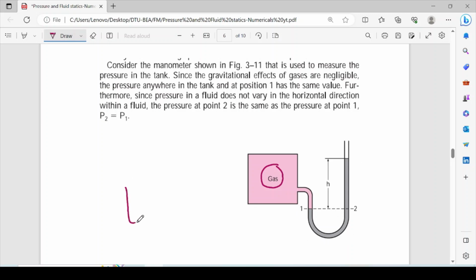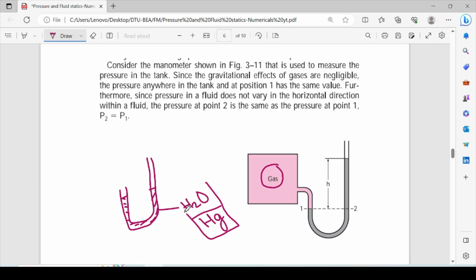Initially, this U-tube manometer is like this, and in this we are filling, initially both ends open, a fluid, either water or mercury, depending on the pressure requirement. Mercury is preferred when we are trying to measure a very large pressure in a flowing pipe or chamber.